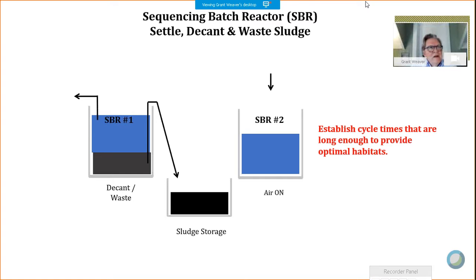So we can monitor and set targets by looking at both the nitrates and ammonia concentrations in a facility to help us set the targets, the process control, the DO, and the ORPs. And we want cycle times that are long enough to get us to a good, strong aerobic condition, and then during the air off to allow that dissolved oxygen to drop, I would say dissipate, to get consumed by the bacteria, so that there's low enough oxygen, then you get into that anoxic state, which you can measure with an ORP.